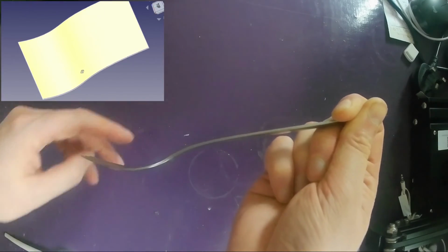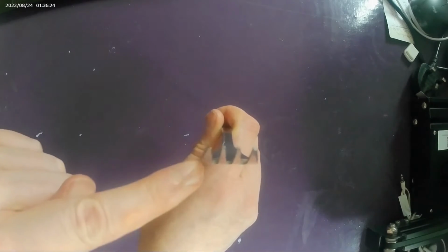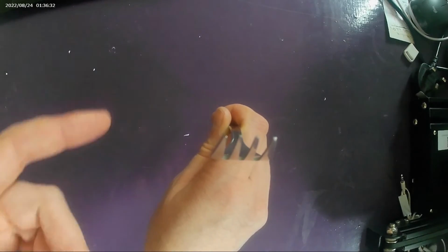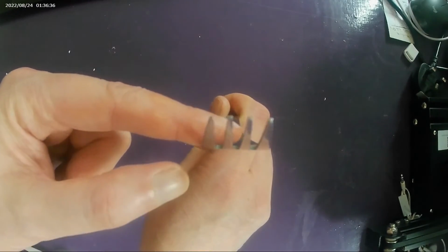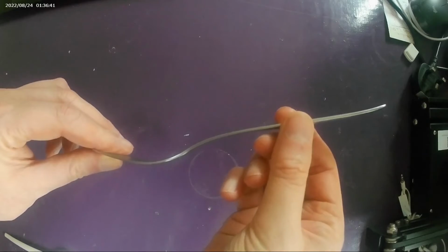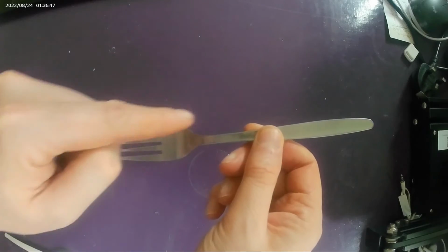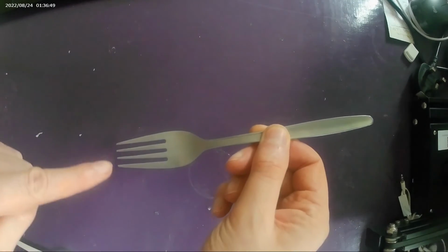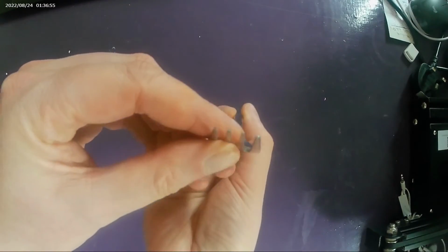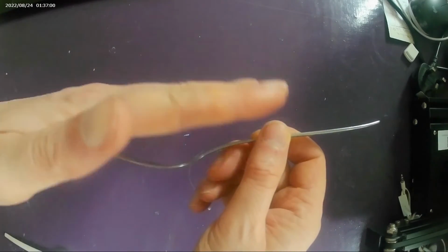Once this goes forwards, then we can tackle it from this way. So looking at any curvature that's coming around here. And then we add this to the model. And we'll probably change the model to something like a sweep or a loft to get that curvature. We're still only dealing with the profile from the side and the curvature from the front. So what you'll end up with is basically a rectangle around this bounding box of the fork. Once we get that curvature, you may not end up with any curvature this way. So it may be just a straight extrude along here going this direction.